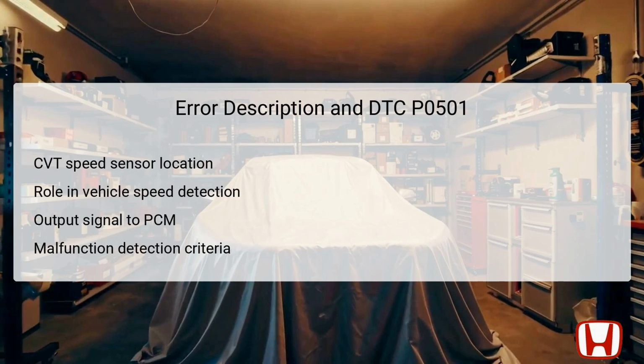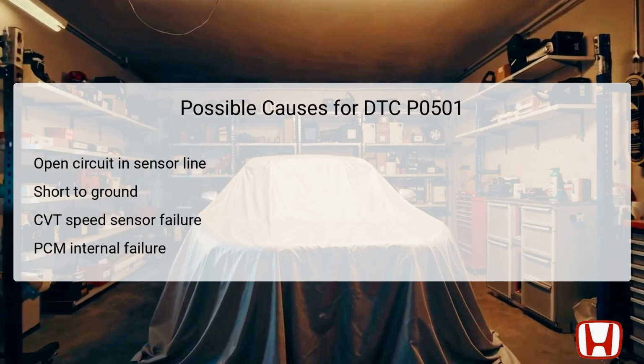Should the sensor fail to send pulses despite the gear rotating, the PCM identifies a fault condition and logs DTC P0501. Monitoring for this error involves a continuous execution of diagnostics that checks various operational parameters, including engine speed, vehicle speed, and the relationship between sensors. If certain thresholds are not met, such as the CVT speed sensor's output being significantly lower or higher than expected, a malfunction is indicated. Diagnosing the DTC P0501 involves understanding multiple potential causes.